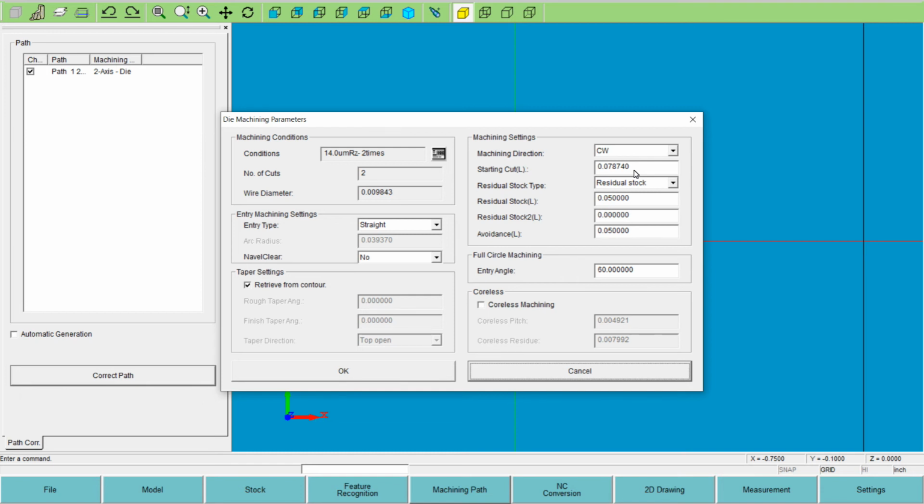I would think you probably have a 1/4 inch, and maybe leave this set to like 1/8 of an inch then. These wire class samples are pretty small, so you want to watch the size we use here. And you leave this on residual stock, and then this will be the tab length, and this will be the pull-off move.